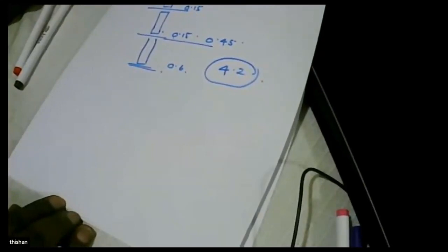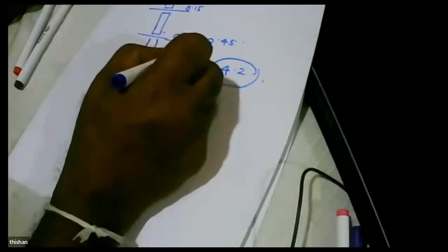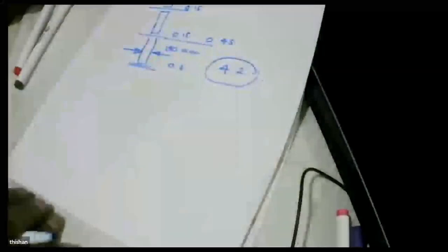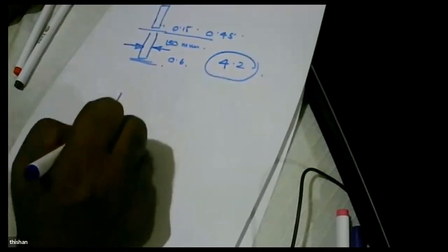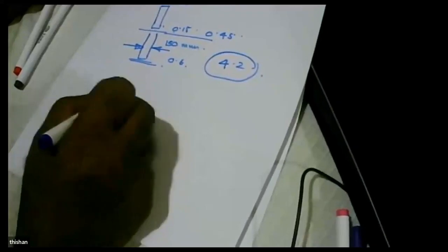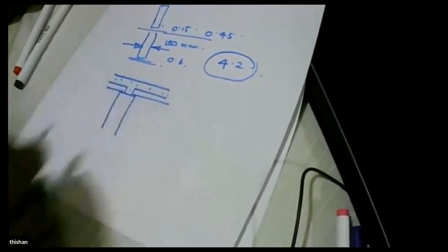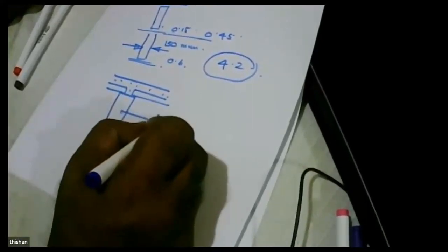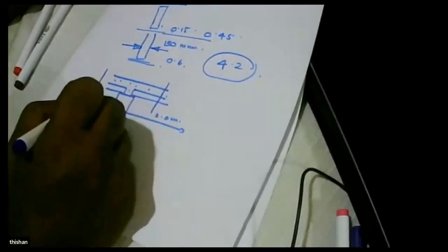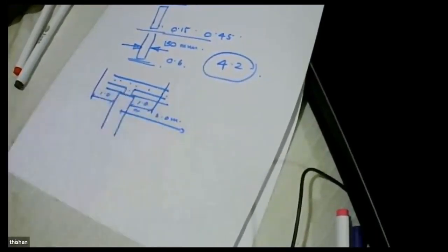So you can see there's a good possibility to complete the walls with a wall thickness of 150 millimeters and still have a factor of safety of over 4.2, provided we place the concrete slabs on the wall directly and make it continuous so that each slab will span 2 meters, providing a load of 1.0 meter width onto this.